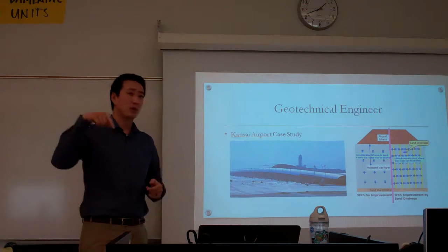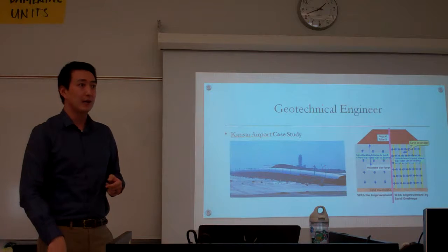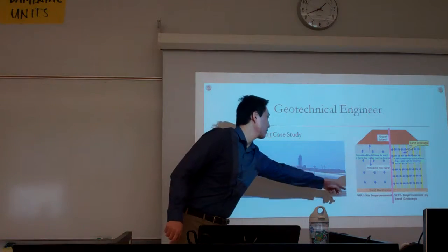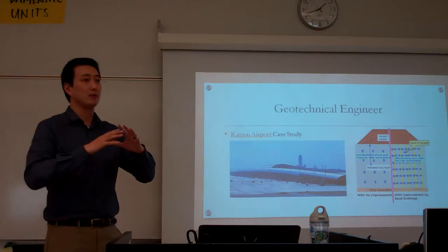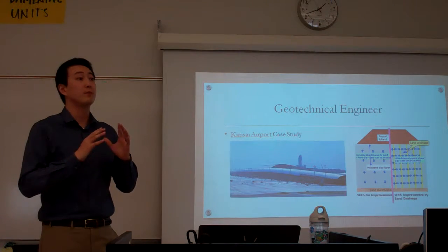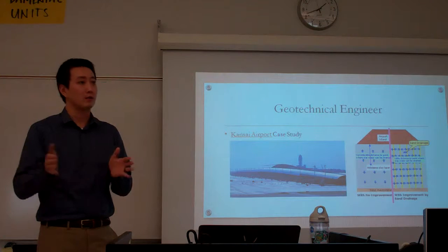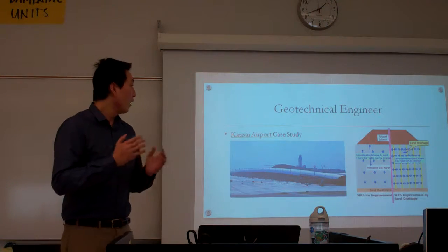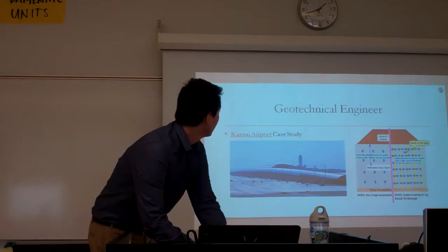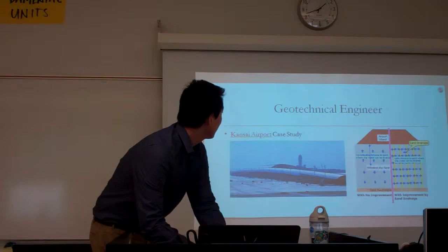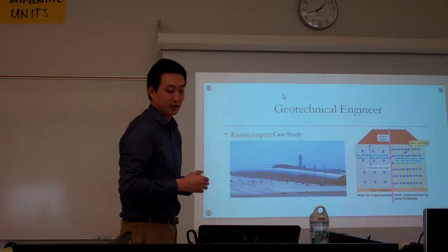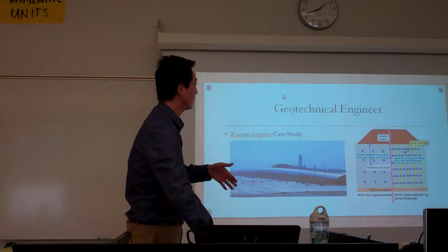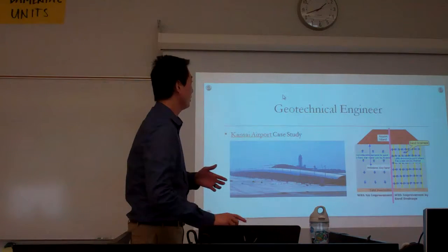They did this by drilling sand piers all the way down to the next soil layer, and they loaded it by putting dirt on it, and basically waited until the water started seeping out. Unfortunately, it was the first time anyone had done this. So as many calculations as they made and as many safety factors as they put in, it wasn't enough.